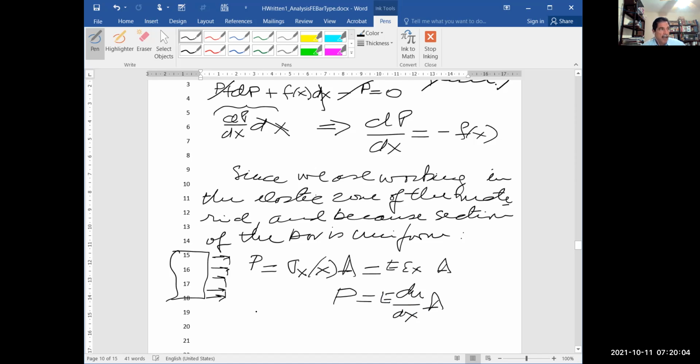So remember this relation. This is a differential equation that can be applied when we have to set equilibrium. If you had a statically determinate case, this is going to be enough. If you have a statically indeterminate case, then you need something else. And that something else is this relation, because in this case, we are using extra information.